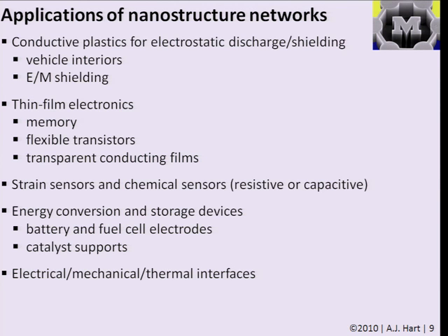In the case of nanotubes in plastics for the mirrors, in the manufacturing process a voltage is applied to the mirror, and because the mirror has a certain amount of electrical conductivity, you can actually charge it. Then the paint molecules get electrostatically attracted to the surface, and that lets them conformally paint the surface of the mirror. That was started many years ago.